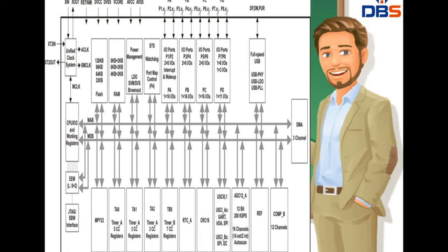During normal operation, the system regularly restarts the watchdog timer to prevent it from elapsing or timing out. So if a system fails to restart the watchdog timer due to any hardware fault, the timer will elapse and generate a timeout signal.